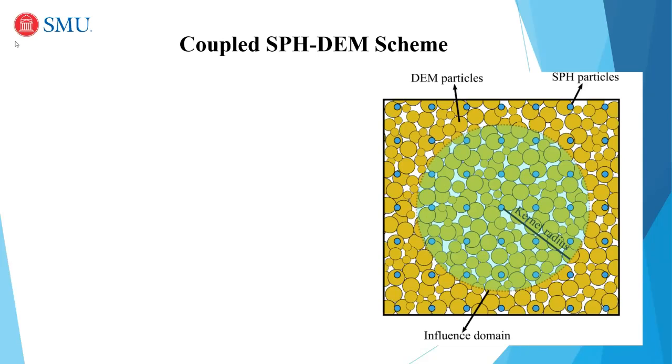On top of the sand, of course, or the void in this case, is full of fluid, water if you wish, and we need a model for also modeling fluid. Now you can model this fluid at different scales. Ideally, to match the idea of modeling the grains at grain scale, is to model also the fluid inside the pores. And that can be done, and I have worked in this area, but as you may imagine, these are significantly difficult and computer and time consuming.